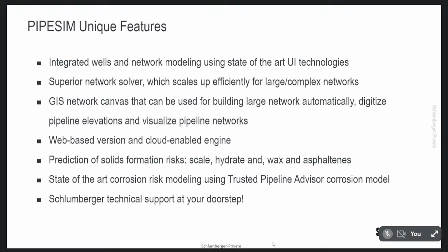And then if you want to link them together, you will need to use lift curves or VLP curves or whatsoever, which will require interpolation at the end. Pipesim doesn't have that. Pipesim can, if you want, work using what we call well curves, but in the natural or basic